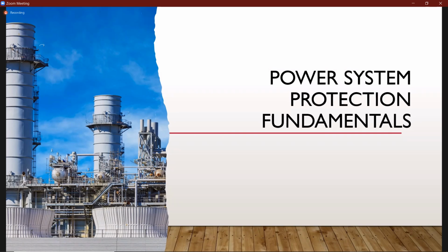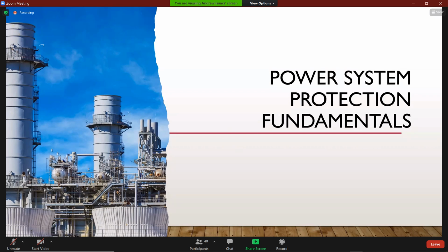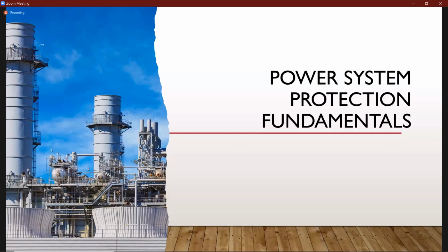So, as a concluding statement, because we're asking what data is required for faults, the data required for symmetrical faults would be your positive sequence information. Yes, positive sequence for your line, etc. However, once you are dealing with an unsymmetrical fault, you require positive, negative, and zero sequence information. And those are the concluding statements that I was expecting. All right. So those are the findings that you should have had from your lab exercise.